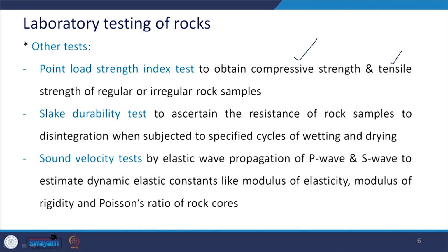Then the next test in this category is the slake durability test, which gives me the idea about the resistance of the rock samples to disintegration when they are subjected to some specified cycles of wetting and drying. So, there is a standard, let us say 2 cycles or 1 cycle of wetting and drying, and from there we try to obtain an index that is an indication of the resistance of the rock sample to weathering. So, this is what we do in slake durability tests.